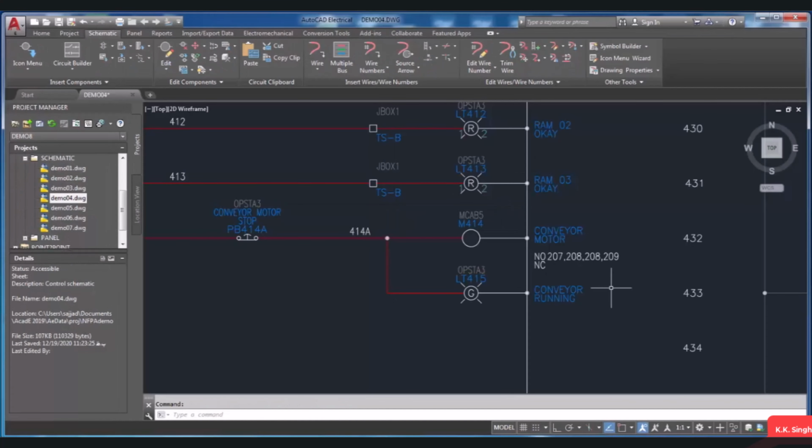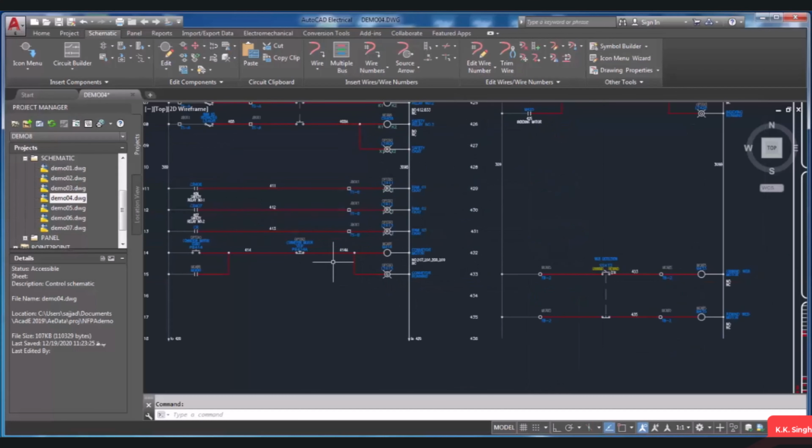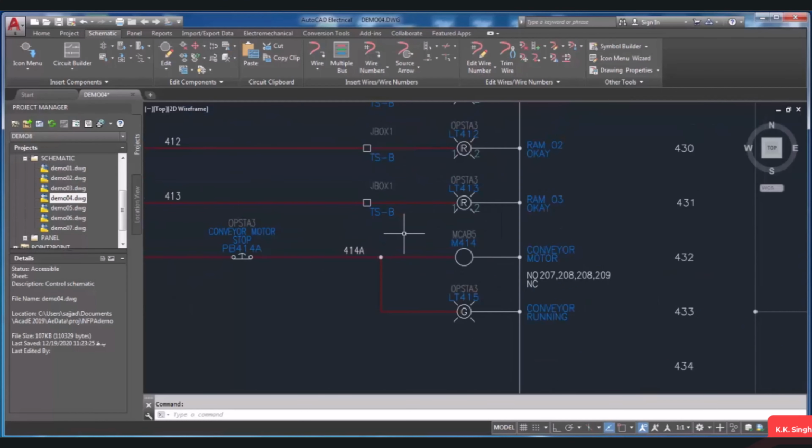You will often need to solve the problems with shorted wires or the wires which are not connected to each other. Therefore, in AutoCAD Electrical, it is possible to check a wire segment or highlight the wires of a wire network. I mean that you can follow the wires segment by segment automatically and solve the problem. Okay, now let's see an example together.